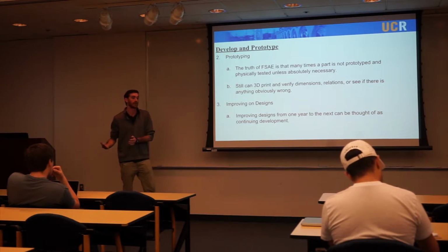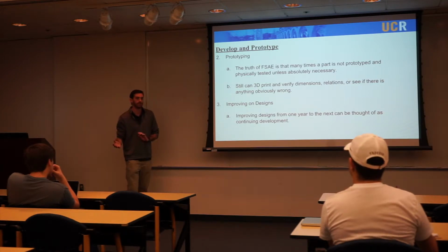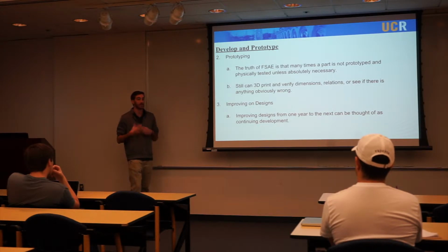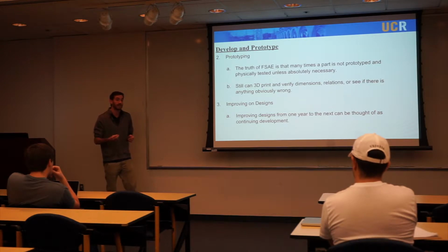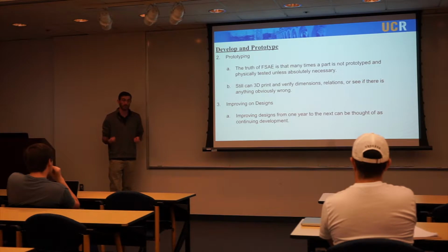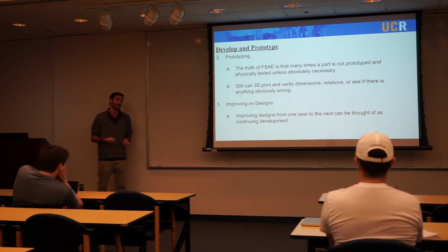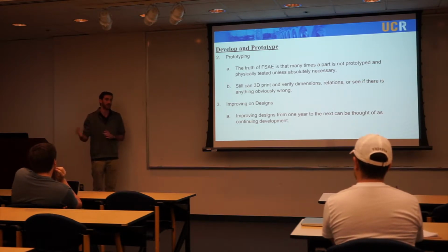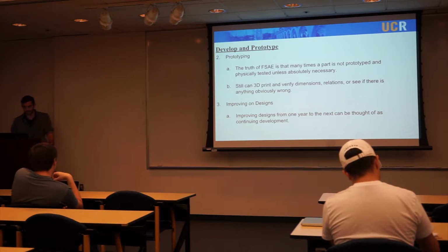Some things need a prototype. The batteries, for instance, like really needed a prototype. The uprights may or may not have a prototype, on the gearing, things like that. Your complex systems are going to have to. And the one thing I can say is if you absolutely need a prototype to validate your designs, do not push it off. It takes a long time to make that prototype and set up that testing. If it's an absolute necessity to validate that design, start moving quicker. And however fast you think you're going, go faster, because it takes a long time. And that's the biggest constraint with FSAE.